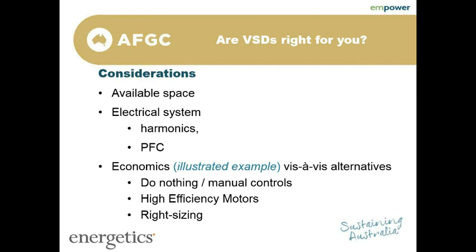So that's whether the variable speed drive makes sense on its own, or you can do some quick calculations and it looks like the costs are too high or the payback isn't there, then leaving it may be an option, or controlling it manually yourself, whether there's staging you can engage on the motor, or just manual controls, conserving energy, switching it off when it's not required, things like that might be another alternative.